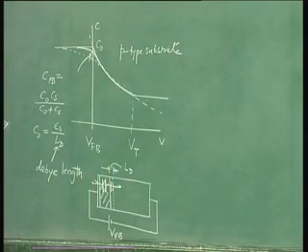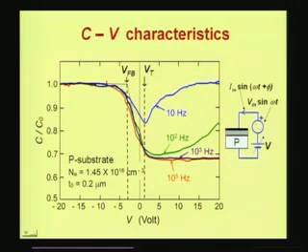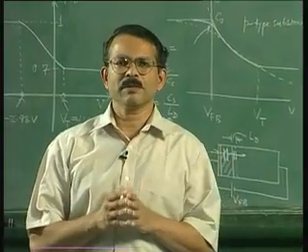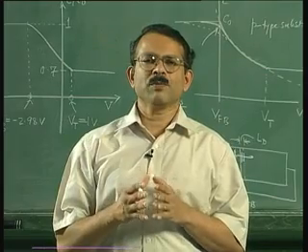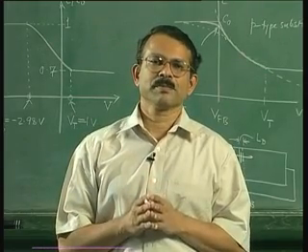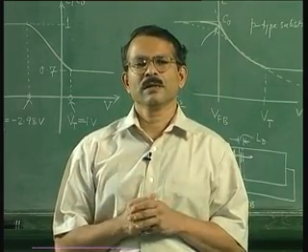So this explains why, although the calculated flat band point is somewhere here as shown on this slide at -3, the actual flat band point could be away somewhere here. In fact, this point has to be located by some involved calculations or argumentation. So we will not discuss this point related to flat band voltage further. We have explained what are the kind of deviations of the measured characteristics from the calculated characteristics.